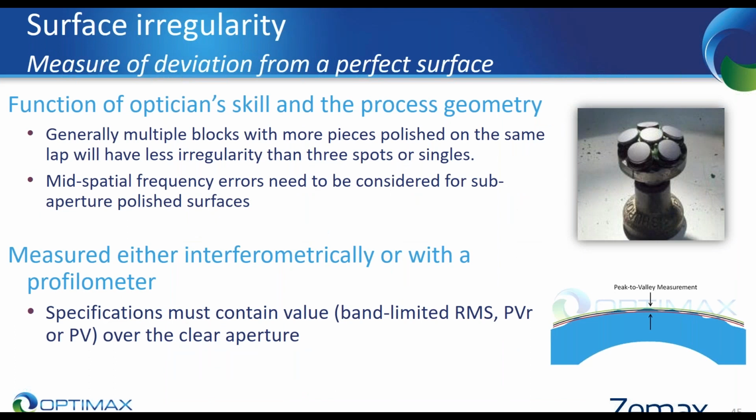But if both are specified, we just want to know why. There may be a good reason, just let us know. One caveat here is power is still useful when tolerancing a plano surface, because a radius tolerance on a plano surface is meaningless.